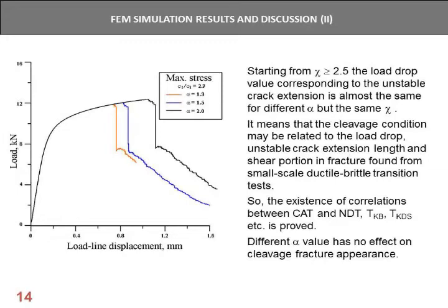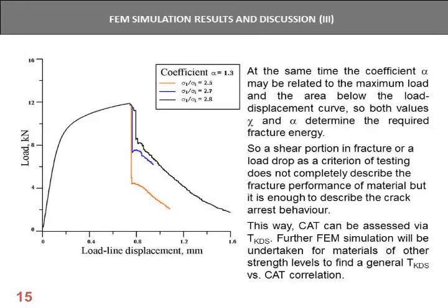Different alpha value has no effect on cleavage fracture appearance. At the same time, the coefficient alpha appears to relate to the maximum load and the area below the load displacement curve, so both values here and alpha determine the required fracture energy.